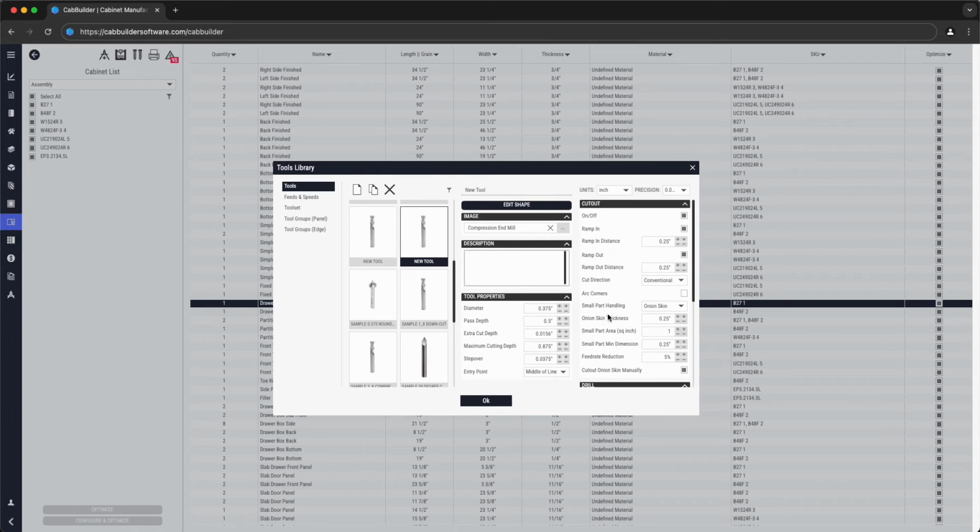You will then enable or disable tool bits for different types of tool paths in the right-hand column, starting with the cutout operation type. Cutout refers to the cuts that fully separate panels from the rest of the material. If you do not intend to use this tool for that purpose, then uncheck the box. Otherwise, activate the operation type by checking the on and off box to be on. The cutout parameters are then defined.